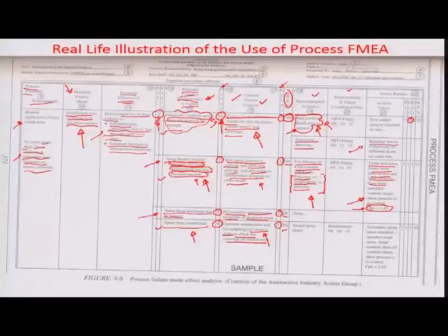So here again the occurrence goes down severely, from 50% earlier to almost about 10%, and that results in an overall reduction in the RPN again. So the RPN changes in the first case to about 70 from 280, and about 21 from 105. There is no need for change of RPN in the third case, that is spray head deform, because the RPN is already quite low. And then in the fourth root cause, that is basically spray time insufficient, again